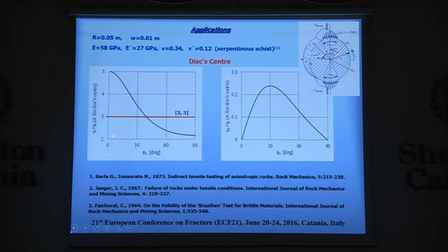And here we have plotted the ratio of the normal stresses, the radial over the hoop one, versus the angle phi0 of the external applied load. And we see that contrary to the case of the isotropic disk, where this ratio is constantly equal to 3, here we see that this ratio varies from 5 to almost 2 as the loading angle changes.